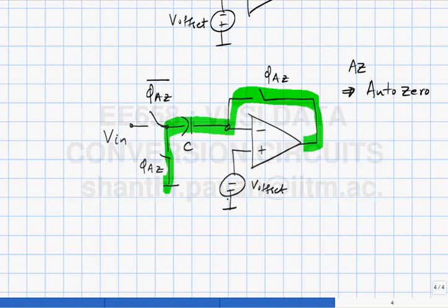You understand? So, whereas in the preamplifier case, when I draw V in versus V out and show a characteristic like that, what do V in and V out mean? They are at the same time. Okay? So, which means that you can use feedback and all this other stuff to find what the input is, what the offset is. Does this make sense? Okay. The peculiarity of the latch circuit and the way it operates, because it's a regenerative positive feedback affair, makes it impossible to find the offset using a straightforward technique like this.